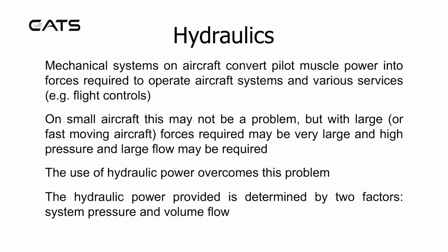Hydraulics. Mechanical systems on aircraft convert pilot muscle power into forces required to operate aircraft systems and various services, for example flight controls. On small aircraft this may not be a problem, but with large or fast-moving aircraft, forces required may be very large and high pressure and large flow may be required. The use of hydraulic power overcomes this problem. The hydraulic power provided is determined by two factors: system pressure and volume flow.